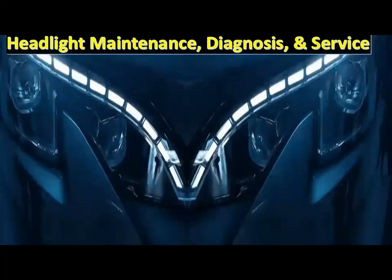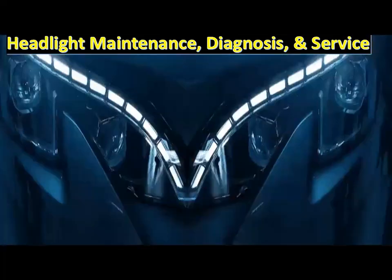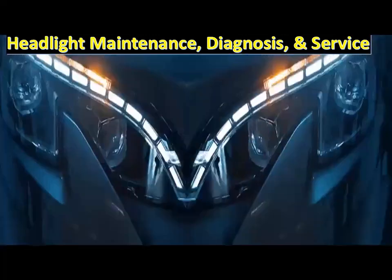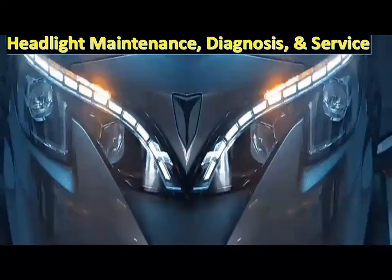Vehicle owners may not be aware that some of the lights on their vehicle are not working. Therefore, the lights should be checked when the vehicle is brought into the shop for service, and any deficiency should be brought to the owner's attention. Headlight maintenance involves checking the headlights each time a vehicle is brought to the shop for service. Be sure to check the headlights on high and low beam, and any other headlight features such as cornering lamps.